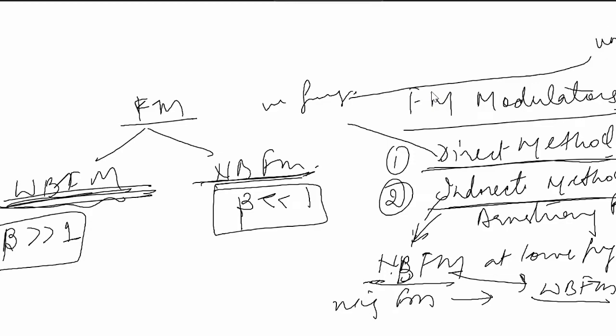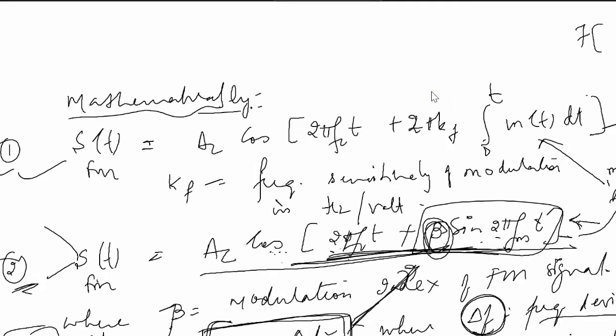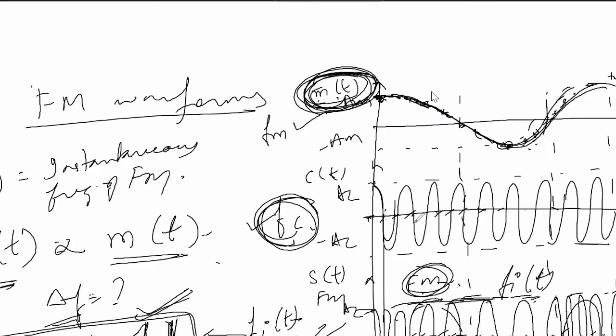If the carrier frequency fc changes on its own, then obviously it has a very adverse effect on FM, because the change in the carrier frequency should ideally happen according to the amplitudes of the message signal in FM, since that is what is carrying the message signal. But if the change in carrier frequency is occurring on its own without the effect of the message, then that will bring ambiguity in the FM output.